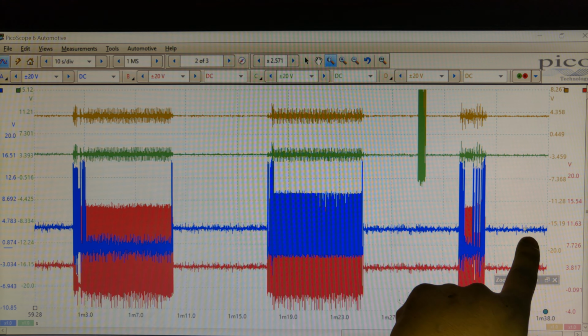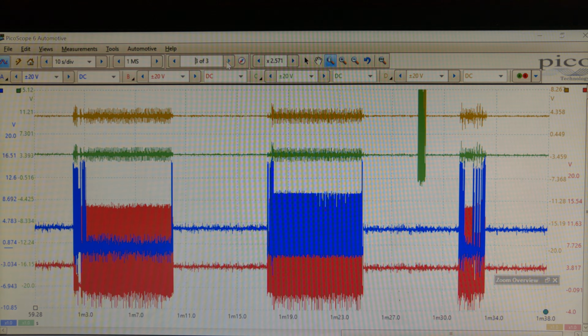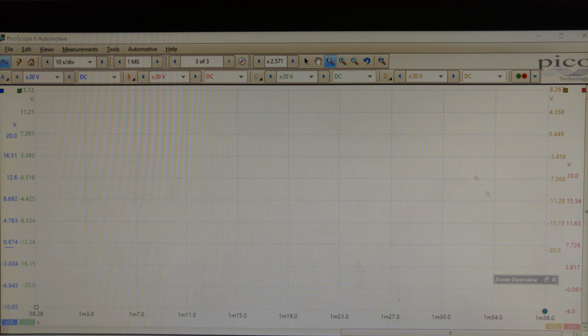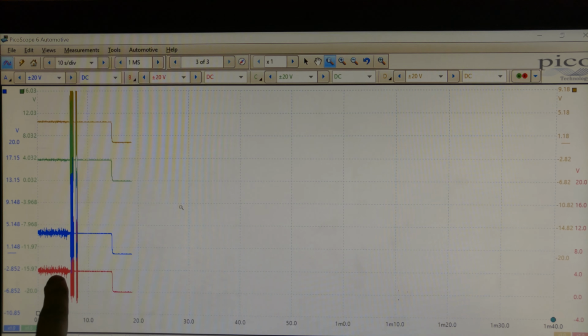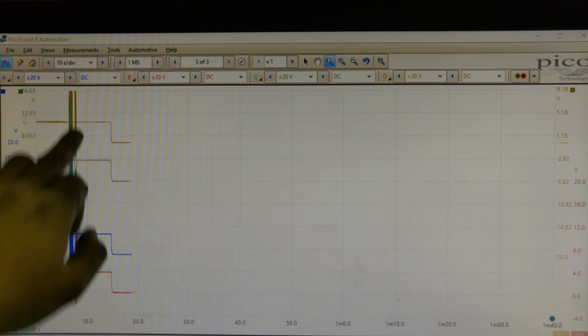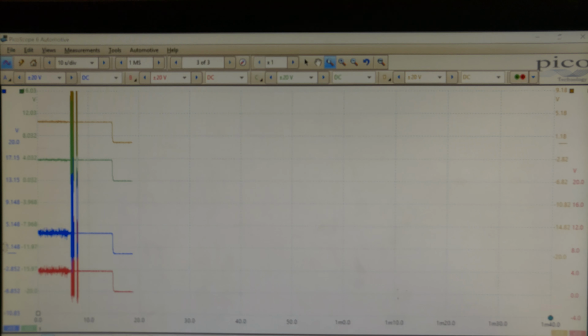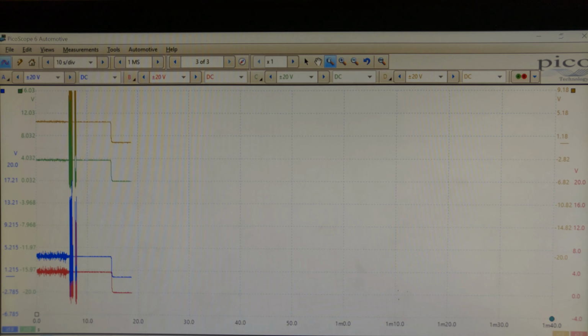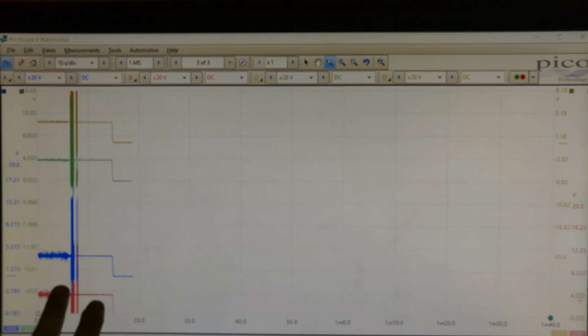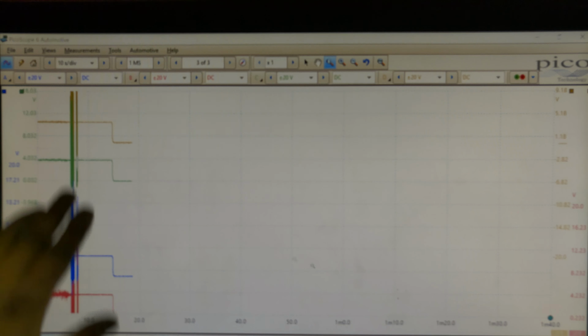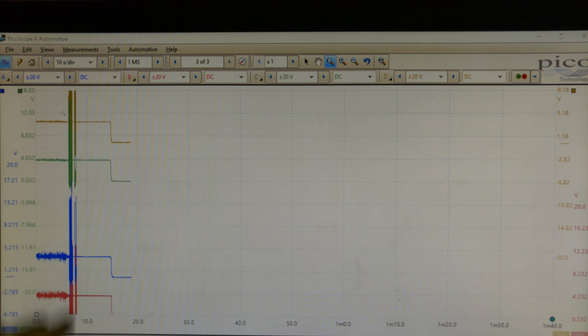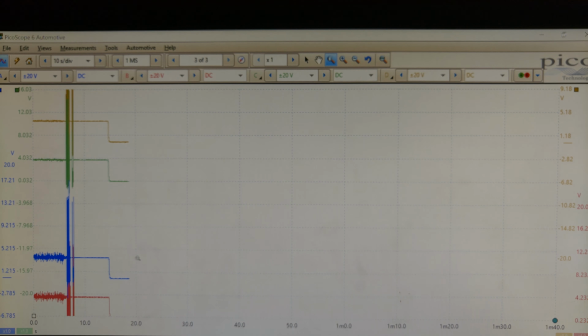And I went back to park there, and next page is, let me zoom out of there. Then I went to park, and then I turned the car off. And when I turned the car off, both actuators are also doing some activity. I think it's just setting to the position where it's going to restart next time. It's easier, it's in neutral, or some sort of activity there, and you can see both actuators are working. And then once I turn the key off, it goes back to 0 volts, all 4 of them.